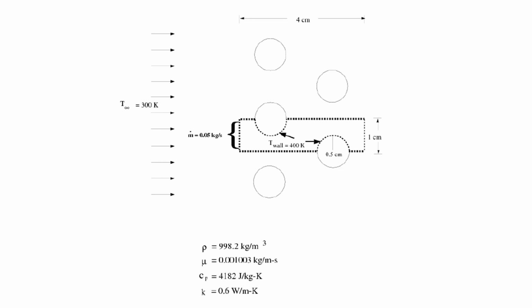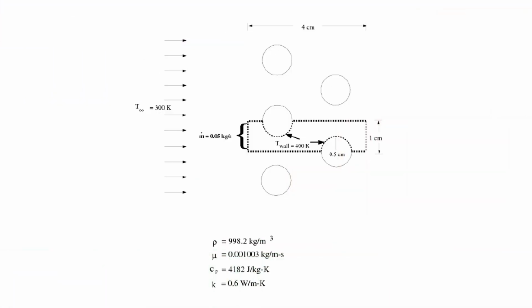In this simulation, both fluids, inside and outside the tubes, are water, with different inlet temperatures. The Reynolds number is approximately 100, indicating laminar flow. Instead of modeling the full geometry, we'll simulate just one periodic module, using symmetry and periodic boundary conditions to represent the entire system efficiently. Thanks to the symmetry of the tube bank geometry, we don't need to model the entire system. Instead, we'll simulate just a small portion of it, which significantly reduces the computational cost.